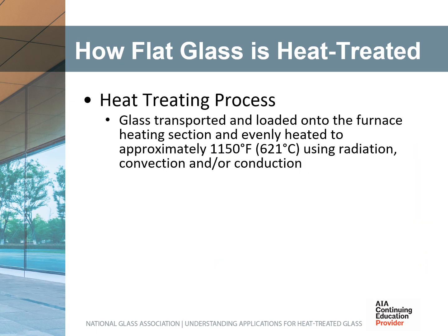Once pre-processing is completed, the glass is ready for the tempering furnace. There are a variety of furnaces available for heat treating flat glass, ranging from small batch to large continuous feed systems, with many features designed to ensure high yield and throughput. However, the basic process has not changed much over the years. As this video from Glaston shows, newer tempering furnaces use convection to heat high-performance low-E glass more quickly and evenly.